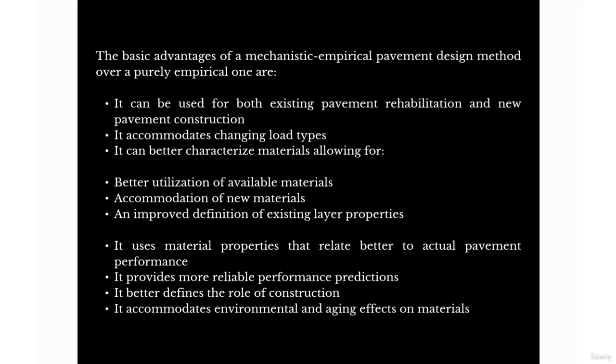So in that case, you'd be using the mechanistic empirical pavement design because it's a specific design for a specific road, and we're dealing with specific material, and it's worthwhile for the client. And that's when we go into aggregate matrices: should you use a geotextile to lock in aggregates to enhance your aggregate matrix, things like that. So that's why it's important, right?